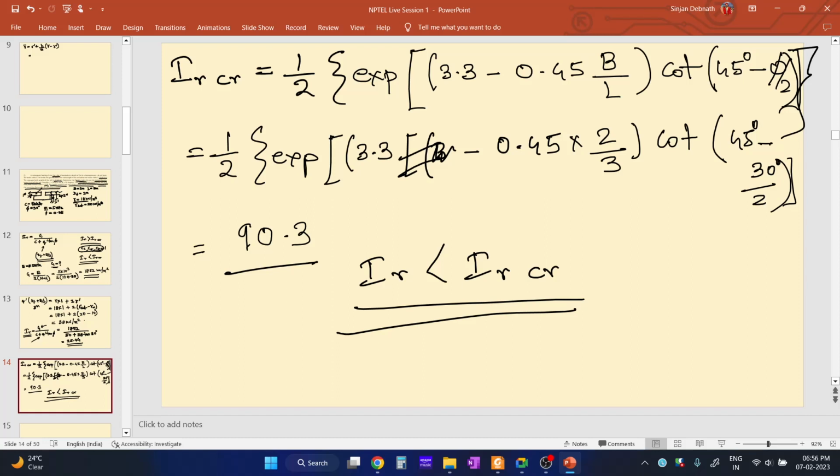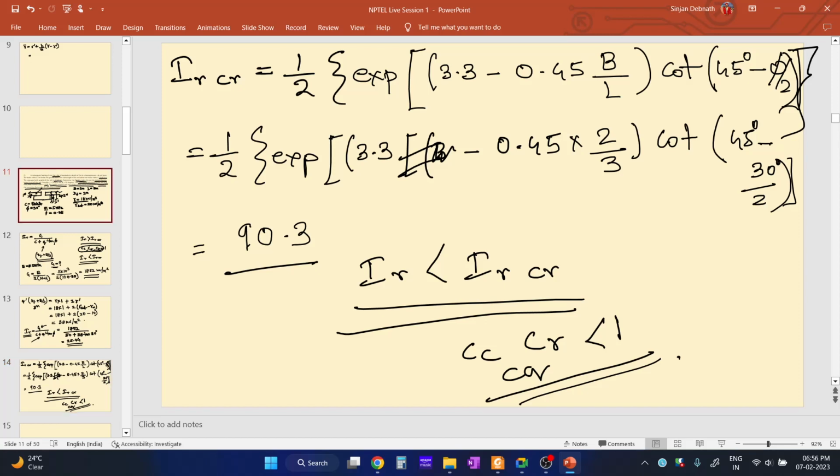So if the soil is compressible, the correction factors, that is Cc, C gamma, Cq, all these factors will be lesser than 1. So this is the comment. All the correction factors which we incorporated into the bearing capacity equation will be lesser than 1.